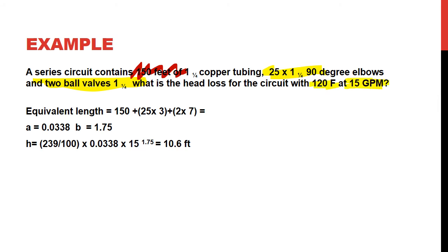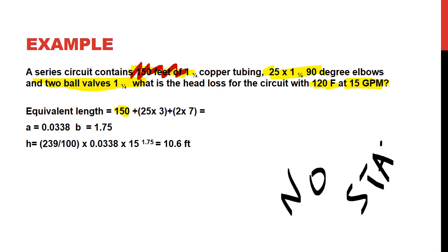That's just a lookup. So I want to find the equivalent length. I have 150 feet already. This is the length of the pipe. I don't have static. There is no static here. So I'm doing only length. So 150 in here, and these are the elbows.